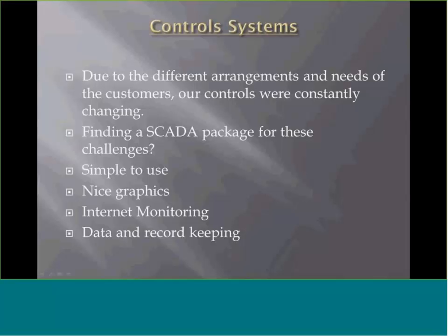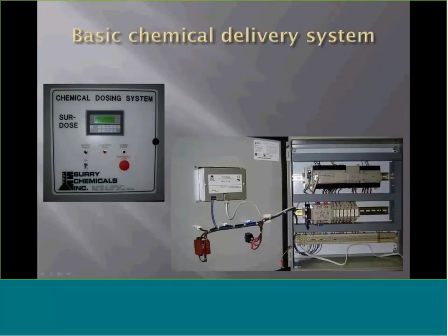All right, I want to show you some examples here. Right here is a basic chemical injection system. It's, like I said, a small screen with a small ARM-run control, and right here I can connect InduSoft. If you look, there's no Ethernet on this one. This is RS-232, something InduSoft can connect to really easily using their drivers for the RS-232.